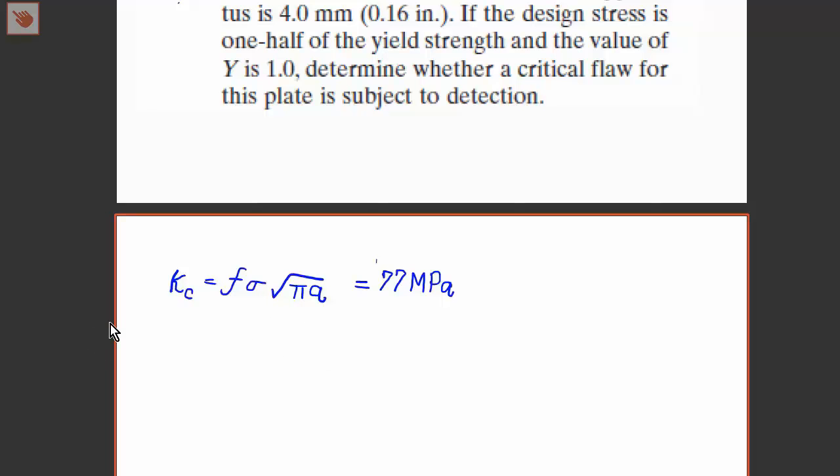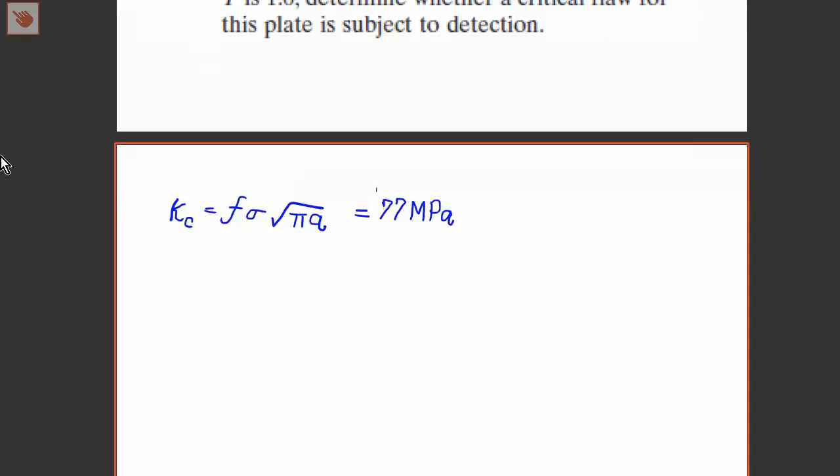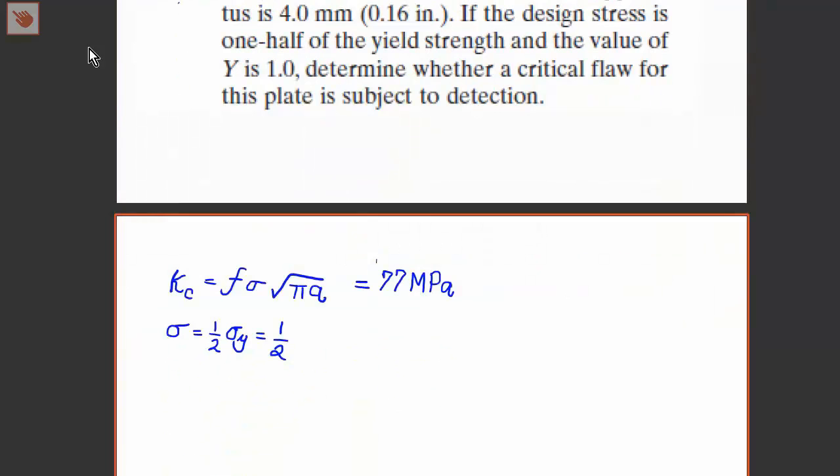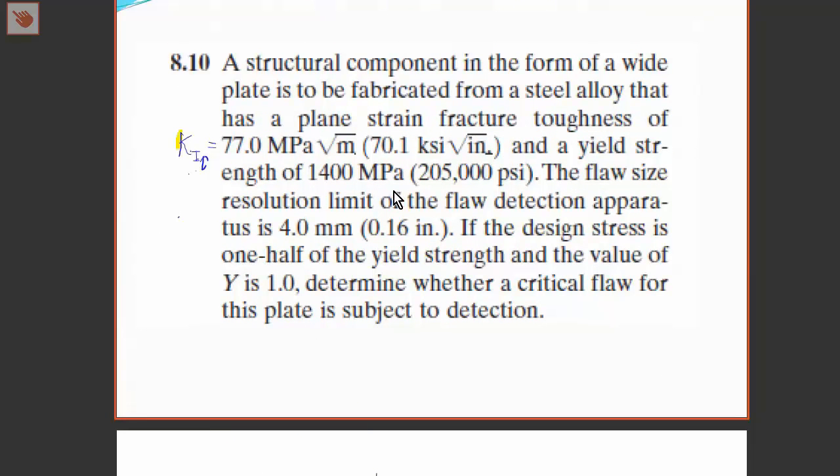Now, we want to determine whether under a load, sigma is, in this case, equal to half sigma y, the yield strength, which is half multiplied by 1400 megapascals. It doesn't really matter whether you use the SI units or the American customary units. You just make sure you're consistent.